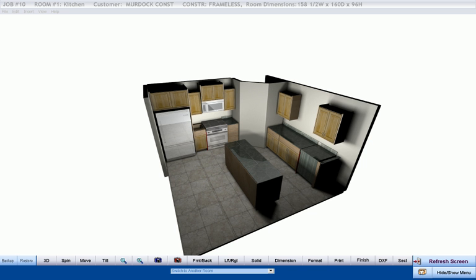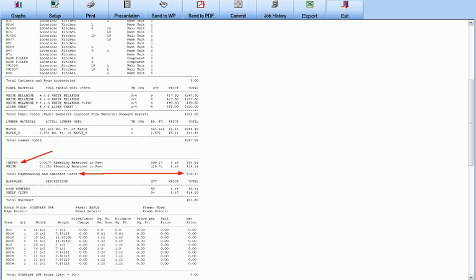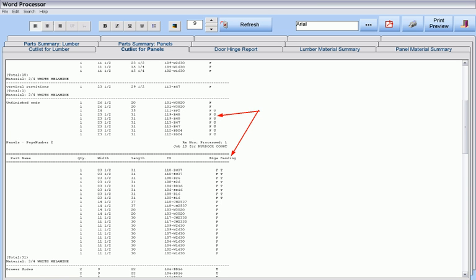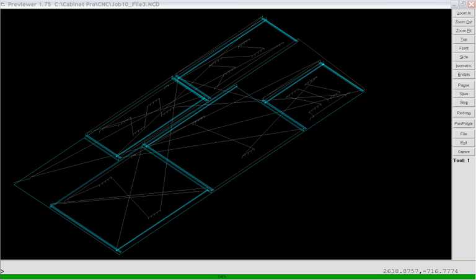This automatic and very custom placement of edge banding that comes from our setup file will be automatically applied to each part during design and will be part of the bid, part of the cut list where the letters F and T that you see refer to front and top, and part of CNC processing as is shown on the simulator, where all machining is automatically moved closer to the side of a part being edge banded according to the thickness of the edge banding on that particular side.